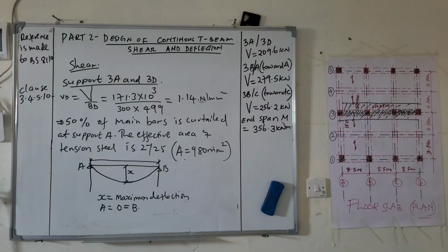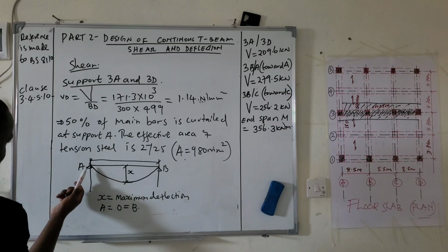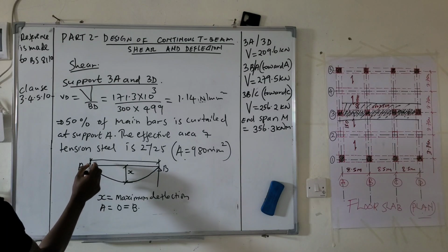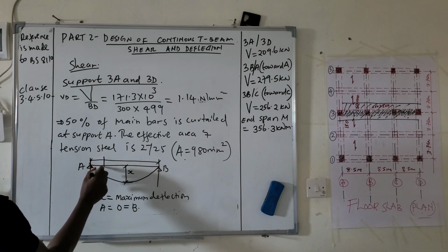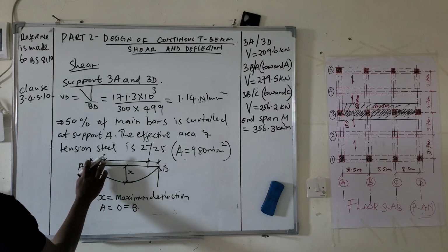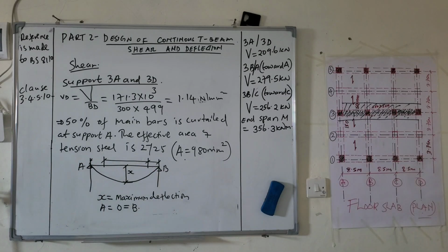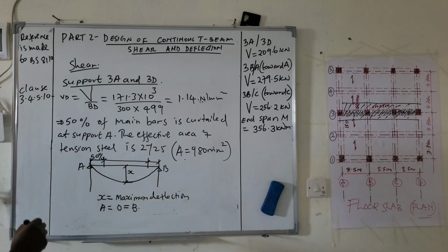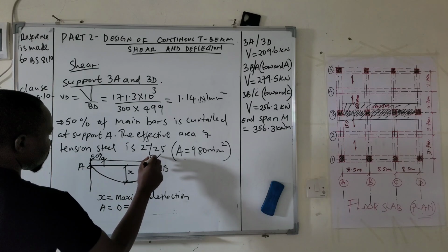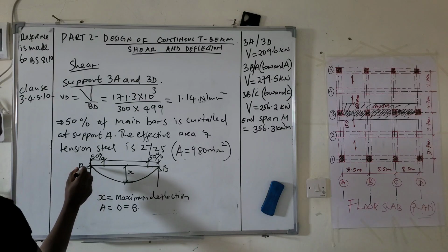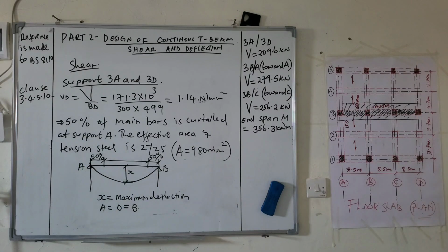The reason is the bending moment at the support is 0. So you can do the curtailment at this support, maybe to a place somewhere like there. This is why you will provide curtailment for some reinforcement. So let's say 50% curtailed and also 50% curtailed, because there is no need for 100% of this reinforcement to reach the support.